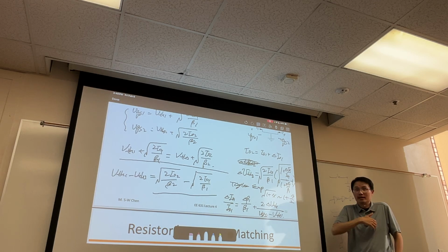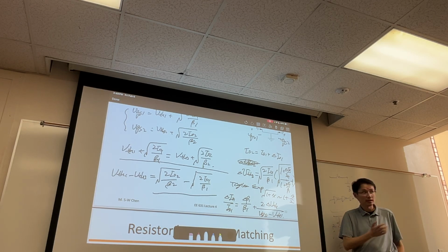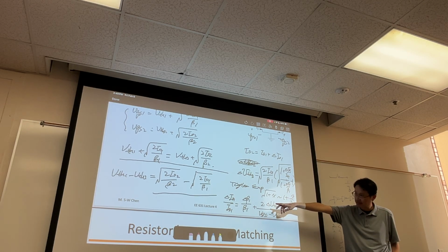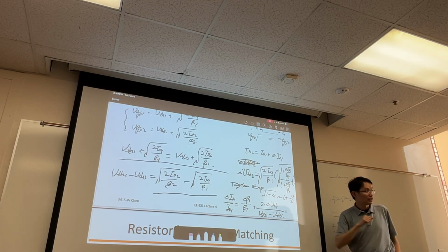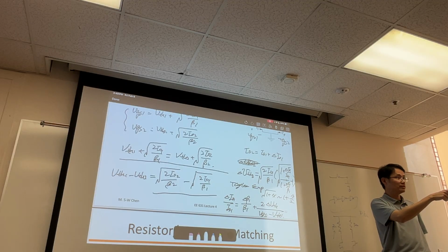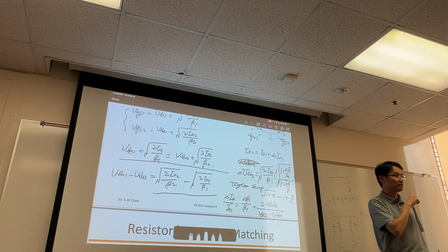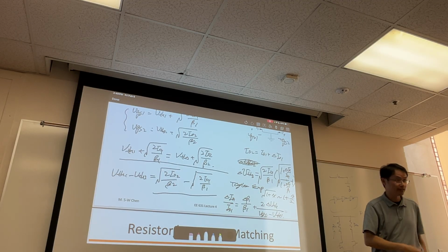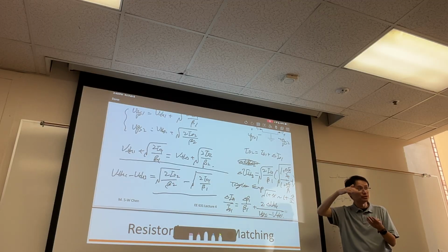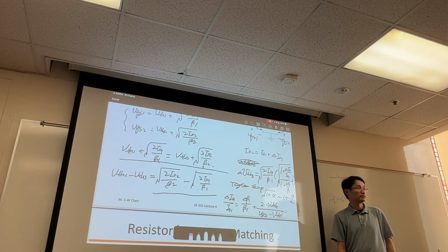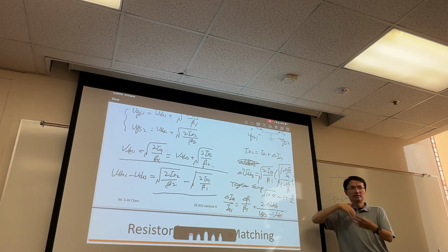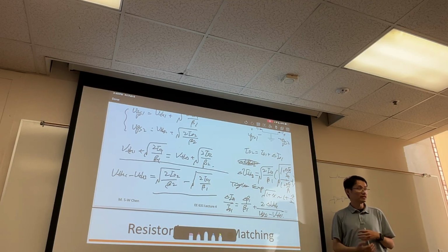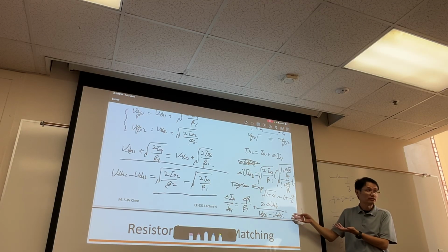So even if you say, hey, I'm using the same sizing for the current mirrors, if you want to make sure that current matches really well, then you use a larger VDsat. What's the downside if I use a larger VDsat for the current mirror? The headroom issue, right? Because at your output, you may not have headroom to sustain that. That's what I meant by why we are learning all this in the analog class, because it gives you insight.